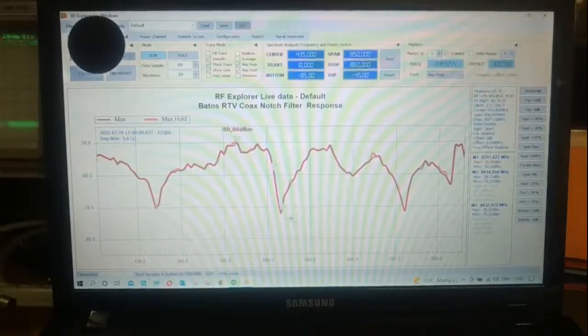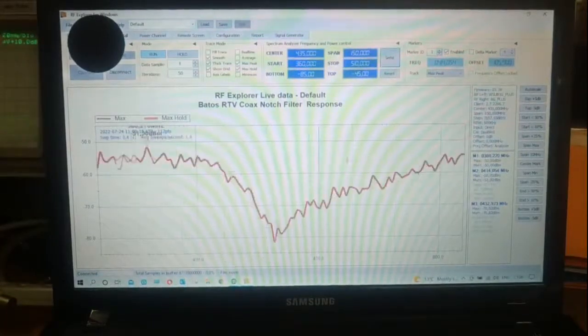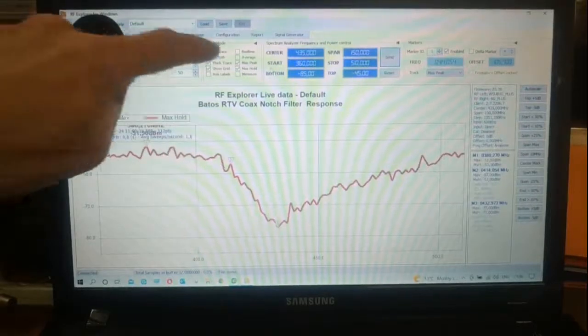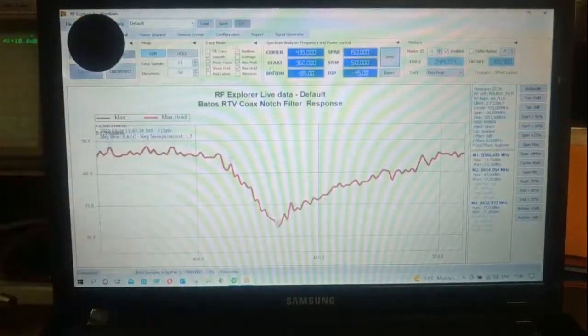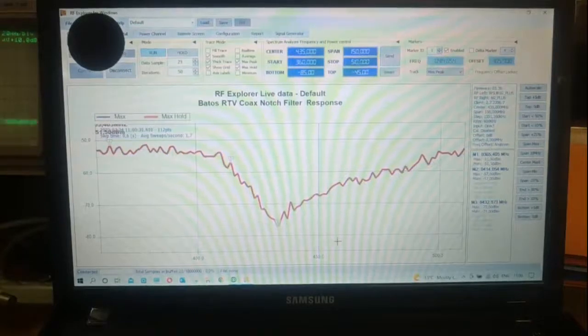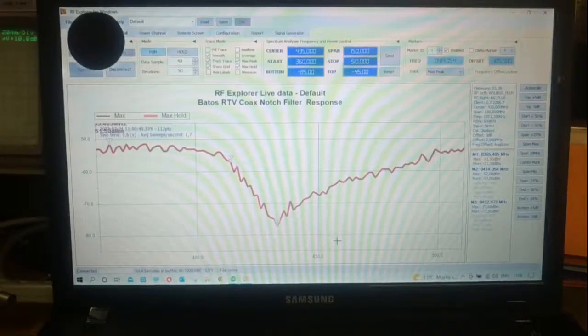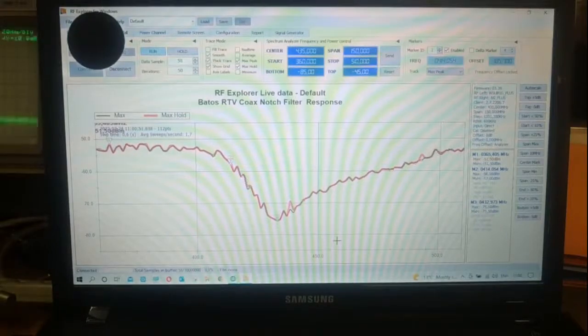So, in a nutshell, let me go back there to R150. So I'm right now at the maximum peak and maximum hold. And of course, it's all a real-time display, which will vary in real time. So I have just demonstrated, with a simple explanation, in the simplest form, that notch filters, yes, they do work, and they are widely used in RF, immaterial of the frequency, whether it's in a gigahertz range or it's HF, radio amateur bands, ultra low frequencies, and so on.